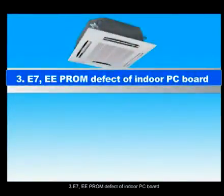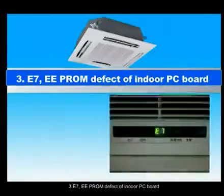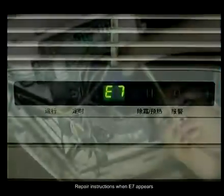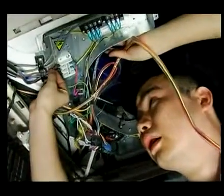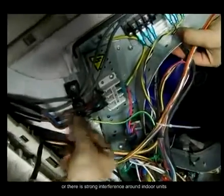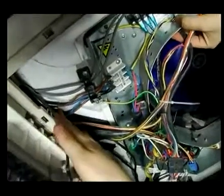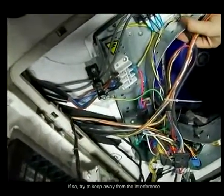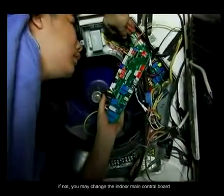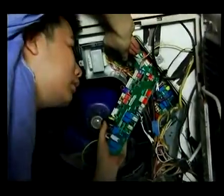3. E7 EEPROM. Defect of indoor PC board. Repair instructions when E7 appears. Check if the electric control wiring is reliable or there is strong interference around indoor units. If so, try to keep away from the interference. If not, you may change the indoor main control board.